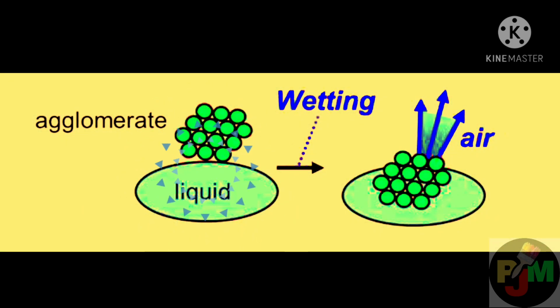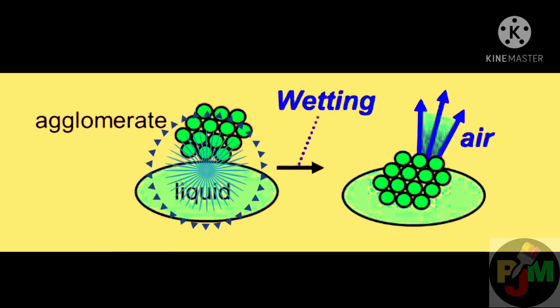But do you know the purpose of pigment dispersion in paint manufacturing? The purpose of pigment dispersion is to replace the adsorbed material on the surface of the dry pigments and inside the agglomerates, such as water, oxygen, air or processing medium used during manufacturing of the pigment, by the resin solution. That is, the solid-air interface transforms into a solid-liquid interface. This overall process is known as wetting of pigment particles.